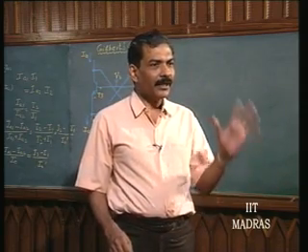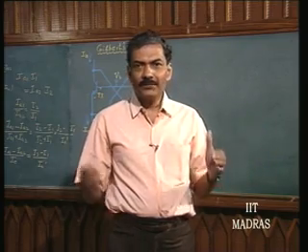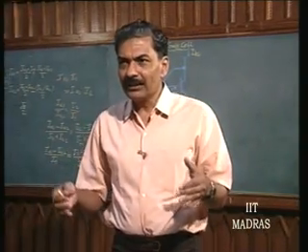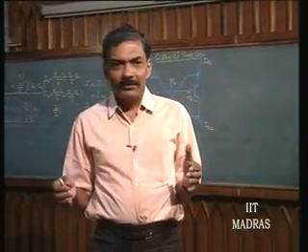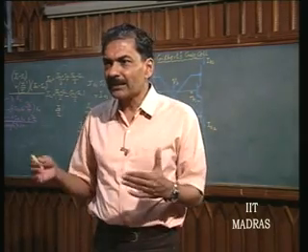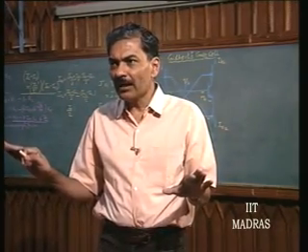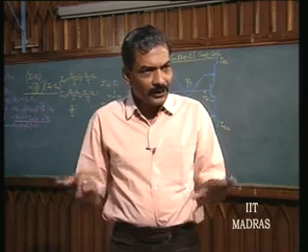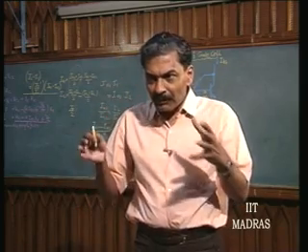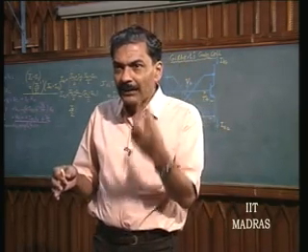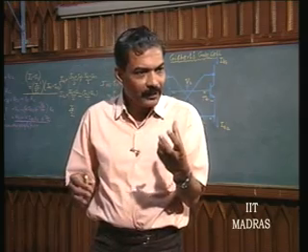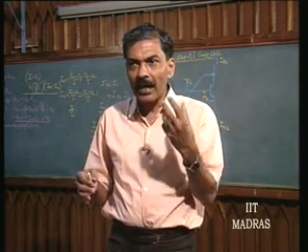This is what you have been trying best to achieve in the case of voltage amplifiers, which you have failed to achieve in a simple manner, which you could achieve only by using feedback, etc. Here there is no feedback at all adopted. Without using negative feedback, I have been able to demonstrate to you that we can get an amplifier, current amplifier, whose amplification factor is absolutely constant.